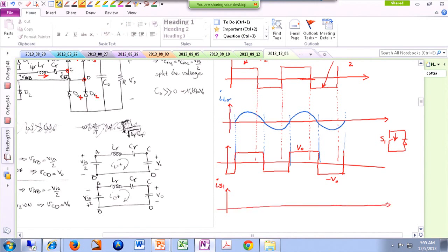okay, this switch and the diode only conduct when the current is positive. So from here to here is my action area, as well as from here to here. Otherwise, this whole thing is not even in the picture. And this switch is only supporting the conduction of the current when VAB is positive. So from here to here, I actually have a command for the switch to turn on, or maybe the diode is on. So the bottom line is this is going to be your current waveform.